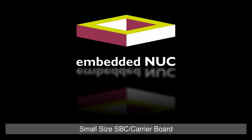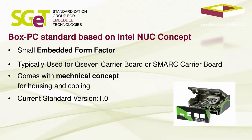The third one is a little bit more special. It's the embedded NUC standard, small size SBC carrier board standard for box PCs. It's based on the Intel NUC concept. So Intel NUC stands for Next Unit of Computing. We've adapted this form factor to make it an embedded form factor for industrial usage, and it's typically used for Q7 or SMART carrier boards, but as you can see in that picture on the lower right, it comes with a mechanical concept for housing and cooling.